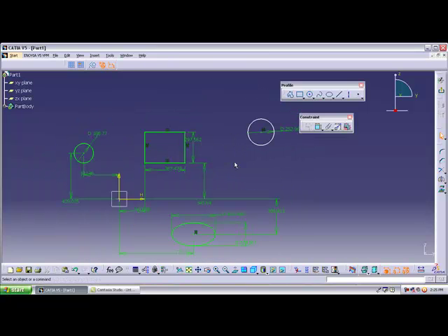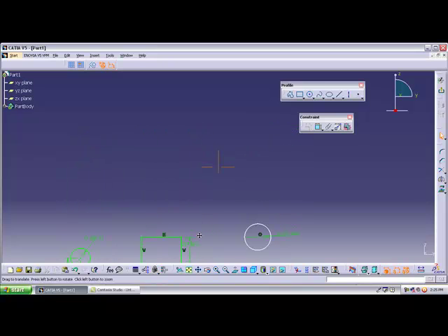So that was a rectangle, a circle and an ellipse, but suppose I have irregular shapes. An irregular shape is, for example, if I am drawing steps, it should look like a small steps shape. See, right now I am getting a problem with the constraints, it's disturbing my constraints. So what you should do is hold the shift button, then the constraints are not highlighted. Or I can remove this circle, nothing will happen. Right now I am not drawing the exact drawing, just a rough sketch.